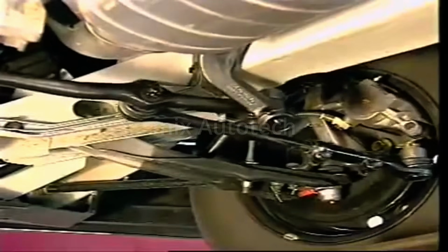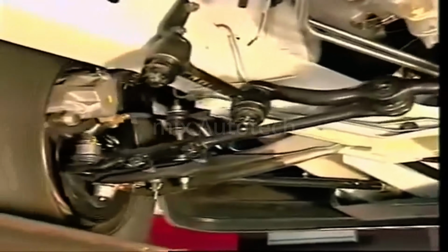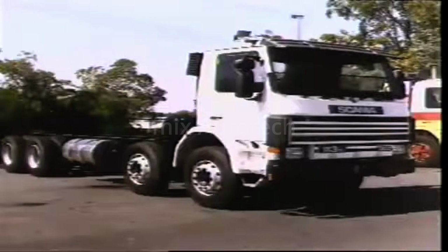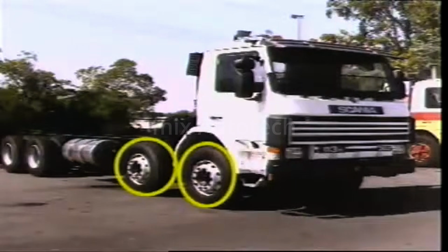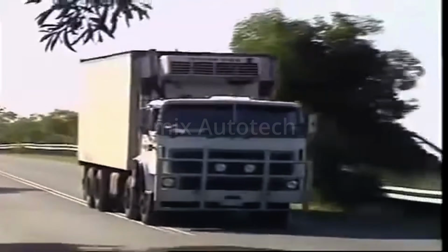This steering system has worm gearing. It provides a gear reduction and a 90-degree change in direction. It has more parts and joints than the rack type, but it is more robust and may be used on heavier vehicles. To allow the heavy transport vehicles to carry extra weight, two steering axles may be used. They're connected by a link to a common steering box. These vehicles are called tandem or twin-steered vehicles.